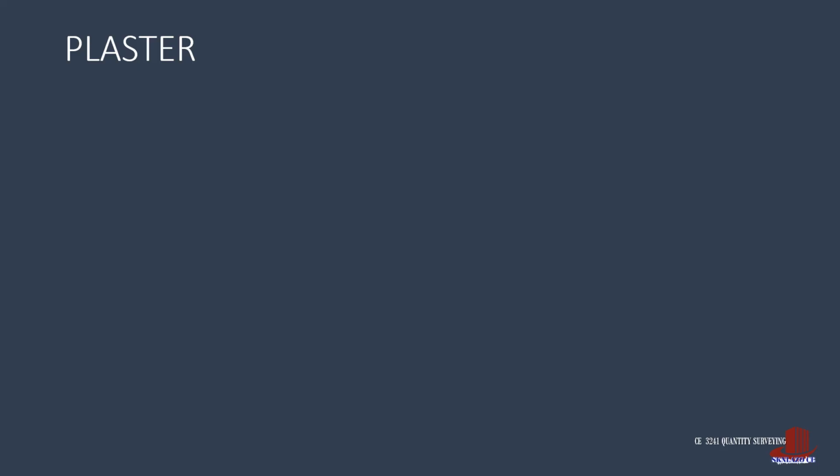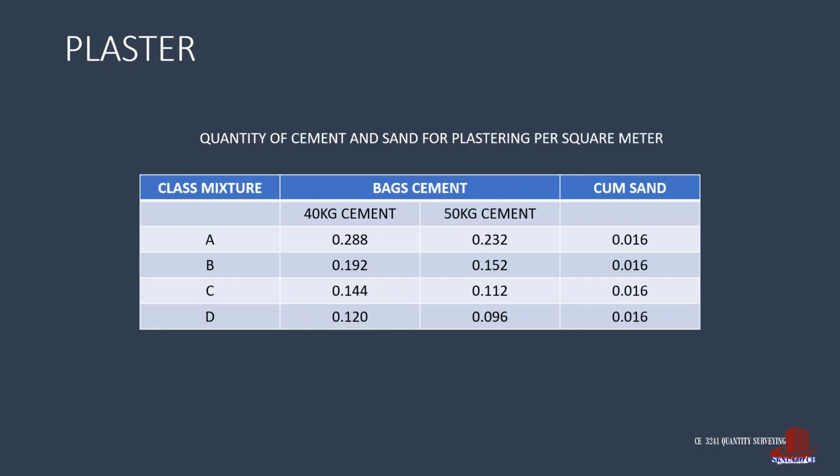Lastly, to finish the wall, one needs plaster. The proportions of cement and sand for plastering are provided in the table, where it will again be categorized on different mixtures from Class A to Class D. Take note that for plastering, fine sand is preferred over river sand.